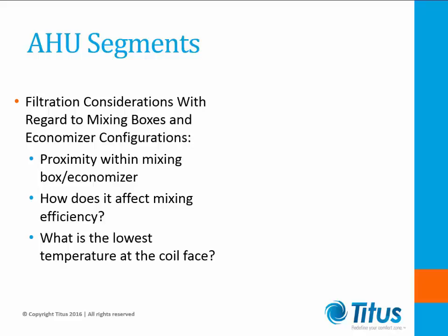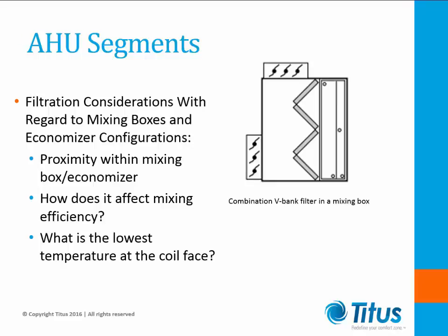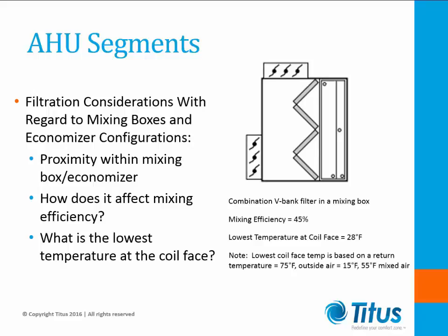Let's take a look at a few different layouts using V-bank filters. Let's start with a V-bank filter inside of a mixing box. In this particular configuration, we see a 45% mixing efficiency, while our lowest temperature at the coil face will be 28 degrees.